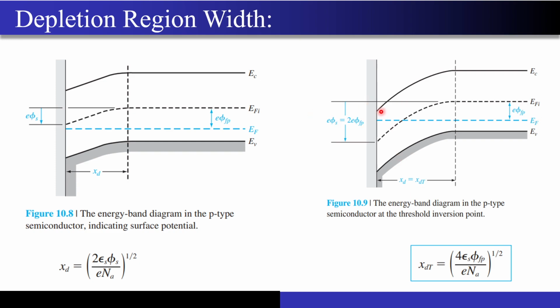And now we define this point, and we said that when this happens, we are pretty sure that an inversion layer will be formed, and our depletion width will not increase anymore, despite the fact that you are increasing the voltage at the gate of the metal. Correct. And we found out that when this happens, the total drop across this semiconductor region is nothing but the total amount of band bending. So if I just calculate this total band bending, that is